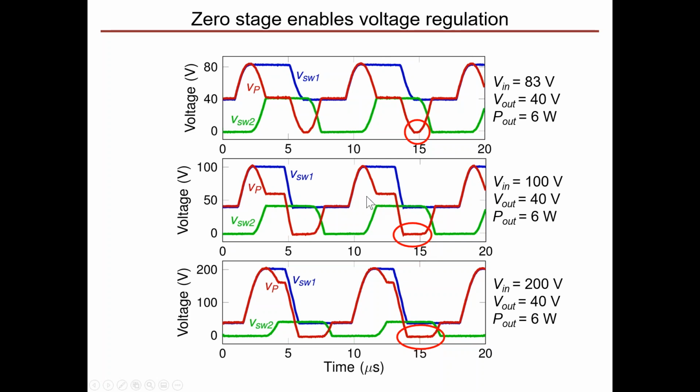And so, for example, this VN minus V out stage, we might choose to leave that on longer if we want to increase the energy that's going through the piezo in a single cycle. And then on top of that, it's just duty cycle and dead time tuning for the appropriate behaviors. Good. Yeah, so it is really tough. Closed loop will be a challenge.